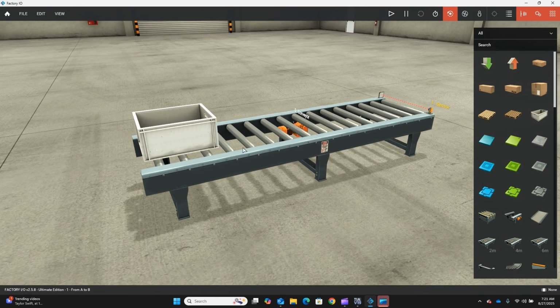And you can see it is just a conveyor with a tote on it. There's one motor that drives this conveyor, so it's all one output. And we have one sensor at the end here. So your assignment is just to write a program that runs this conveyor and turns off on the sensor so the box doesn't fall off.